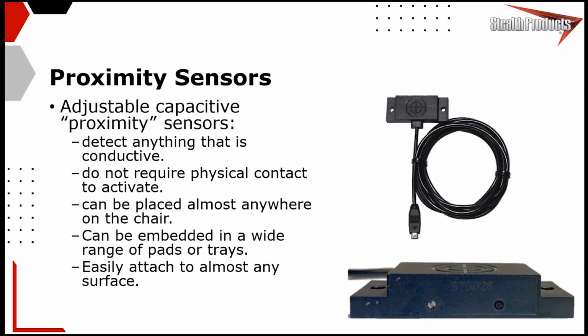Every proximity sensor we use at Stealth is the same one. It's always going to have an adjustment screw here, this little guy right here, and that will adjust its sensing distance. You have a little light over here that shows activations, but these are really adjustable. They're meant to be reliable within about a 1 centimeter field, right?